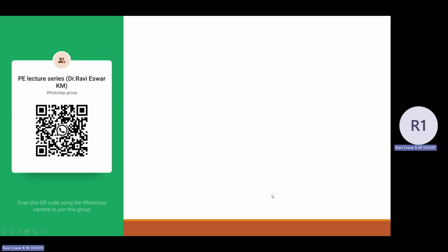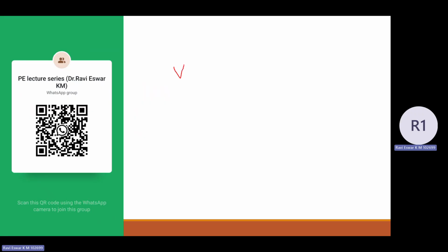In the previous video lectures, we discussed the importance of power electronics and the motivation behind it, and then we started deriving a chopper. So what is the issue with the chopper? Based on that, we came up with the design called a buck converter. Then we derived the output voltage for the buck converter as V naught equal to D into VDC.